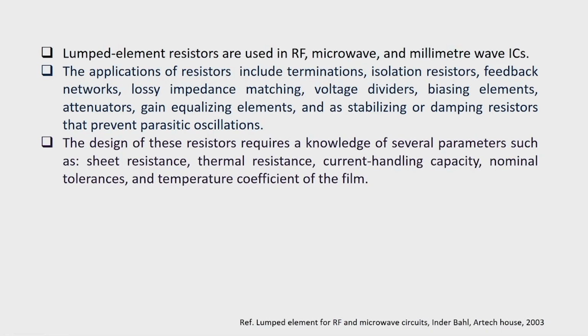Films are used for realizing resistors, and since the purpose of the resistor is to dissipate power, the temperature of the films rises, and therefore, it is important to know about the temperature coefficient of the films.